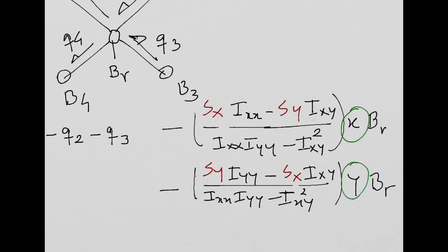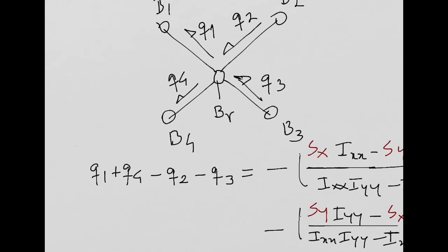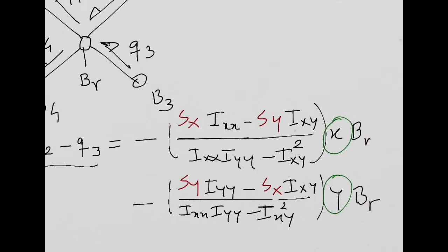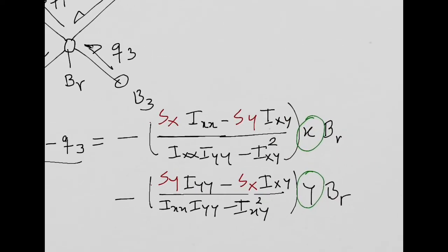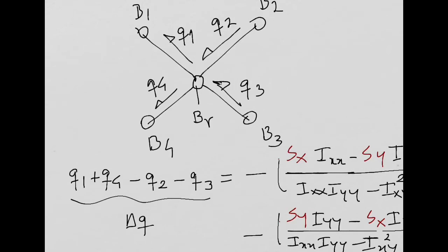And then I need to say, this is going to be equal. Okay? So look at this. When I cross boom R, this is going to give me the balance or the variation of the shear flow, the total balance of the variation of the shear flow. And that variation needs to be equal to what I have here on the right-hand side. And I know everything because this x, y, B_R is the area and the coordinates, the distance to the neutral axis of the boom that I am crossing or doing the analysis, okay?